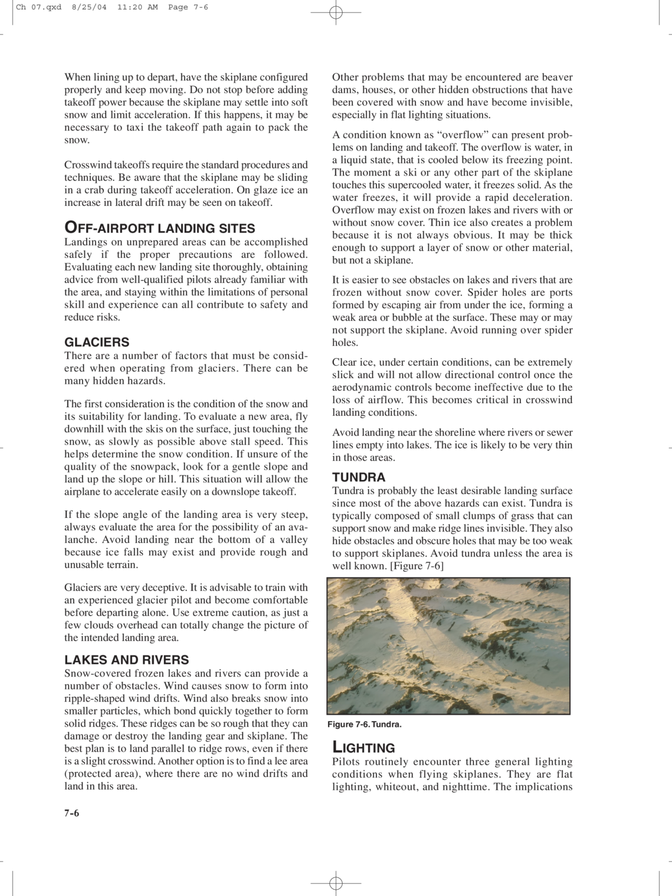Clear ice, under certain conditions, can be extremely slick and will not allow directional control once the aerodynamic controls become ineffective due to the loss of airflow. This becomes critical in crosswind landing conditions. Avoid landing near the shoreline where rivers or sewer lines empty into lakes. The ice is likely to be very thin in those areas.